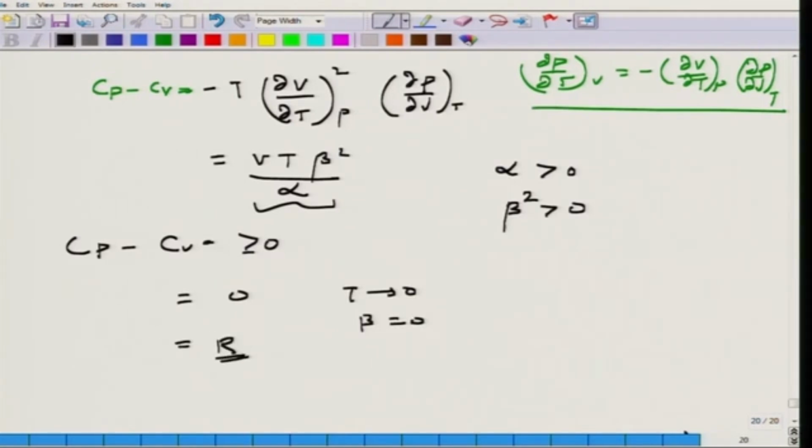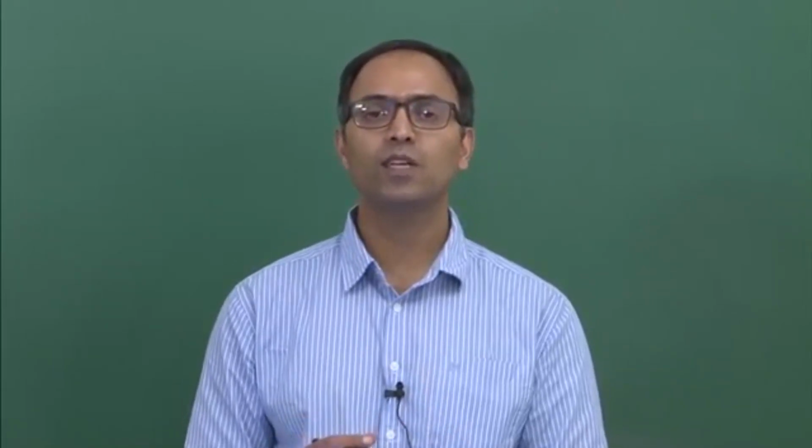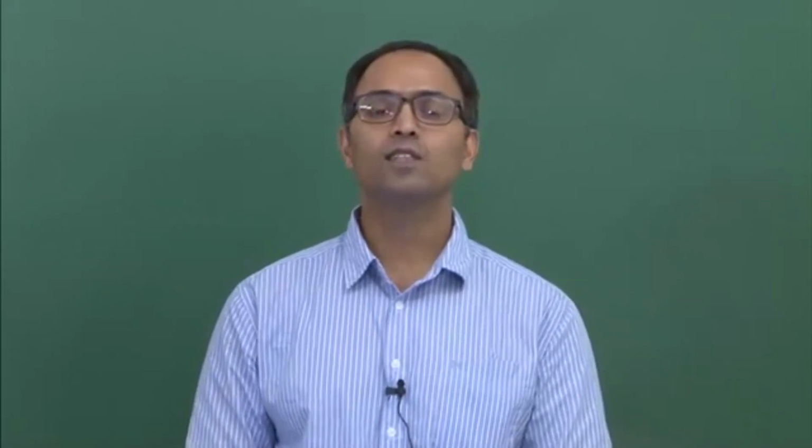So with this, of course, we showed that Cp is greater than Cv with the formal expression. And I think what we went through in this particular set of lectures is to find out the changes in the variables which are of interest, but which are not directly calculated or measurable from the experiment. But what we can do is make use of Cp, Cv and the PVT relations and the set of derivations which we did, and then making use of the cyclic relation and Maxwell relations, we can calculate the changes in the desired thermodynamic properties. So with that, I'm going to end this particular lecture, as well as this topic, and we'll start a new topic in the next lecture.